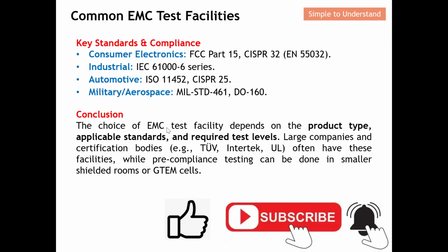The choice of EMC test facility depends on the product types, application standards, and also the required test level. Large companies and certified bodies often have these facilities, while pre-compliance testing can be done in a smaller chamber